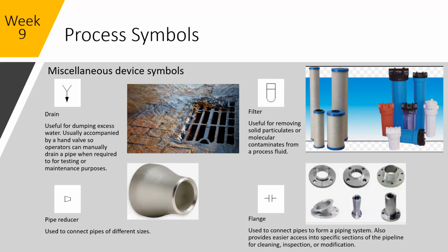And then this is a flange. Flanges are used to connect different pieces of pipe to one another. There'll be flanges on pumps, flanges on instruments. Depending on the size of the pipe, the size of the flange may change. This would indicate a blind flange, where two pieces of pipe would meet with nothing in the center. Flanges are really just the connection points between anything. If the pipe needs to bend, if you're putting in elbows or 90s, flanges everywhere. And the size of the flange is dependent on the pipe and the application.